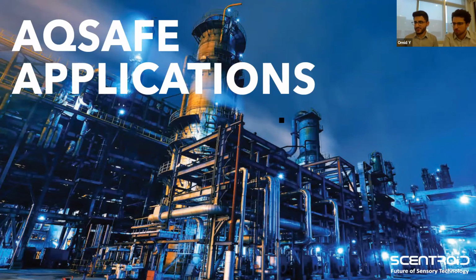The next question is, can you calibrate the sensors yourself? And do you need a calibration gas for some of the electrochemical sensors? So the answer to that is both yes and no. If you have our GD600 unit, we can send you instructions on doing it yourselves. But we do recommend to have the calibration gas for the electrochemical sensors. But we can also perform calibration using co-location as well.